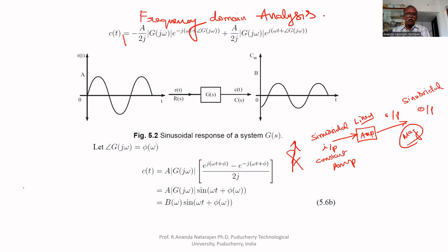Finally, you will draw the frequency response. You will take a logarithmic scale on the x-axis and a decibel scale on the y-axis, and draw the frequency response for that amplifier for different input frequencies. You will get a response like this, a trapezoidal shape.